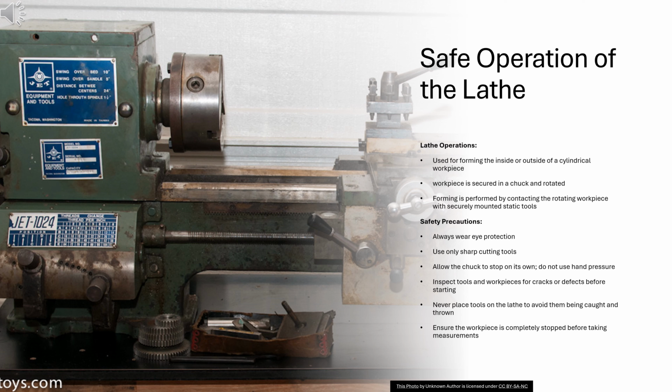To ensure safety, always wear eye protection and use sharp cutting tools. Never attempt to stop the chuck manually. Instead, allow it to stop on its own. Inspect tools and materials for any cracks or defects before beginning. Additionally, never place tools on the lathe, as they may be caught and thrown by the machine. Finally, always wait for the workpiece to stop completely before taking any measurements.